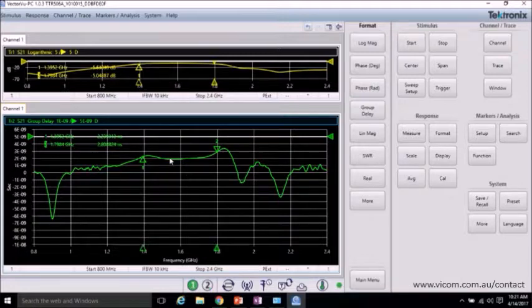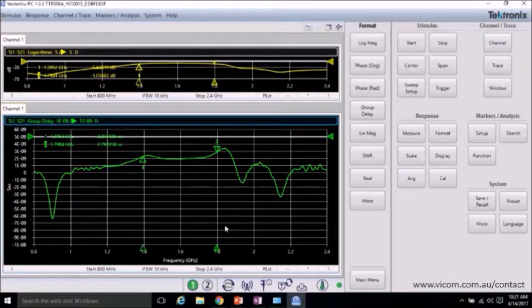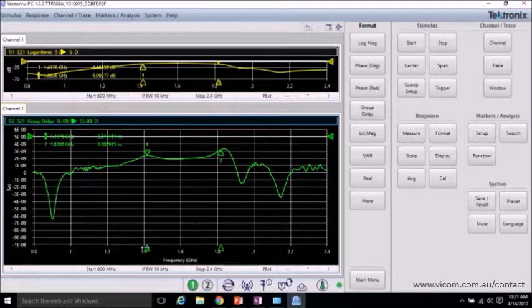And you can see through the passband of the filter, it's relatively flat, which is good. But there are some deviations from linearity. These deviations from linearity can be the cause for distortion through our device. And if we wanted to, we could measure the peak-to-peak deviations. And these deviations are often specified in the device under test data sheet.